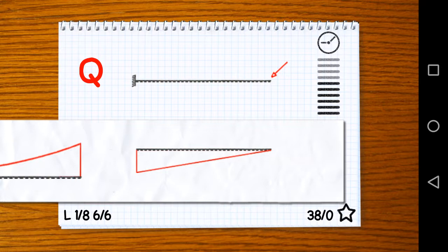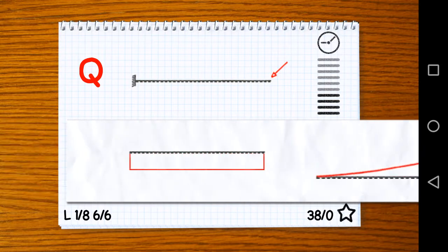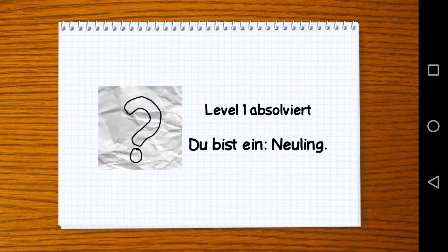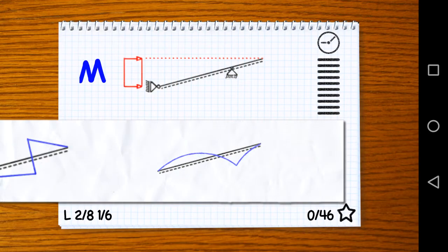So what do we get? A jump downward. So at the end of the beam, a jump downward. This case is wrong. The middle one is wrong too, a jump downward. This one is right. Then it's constant because we have no distributed load. And then at the left side, the support is basically a force going upward. The reaction force of the support, of the clamp support.